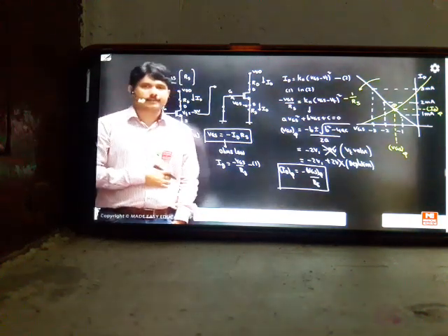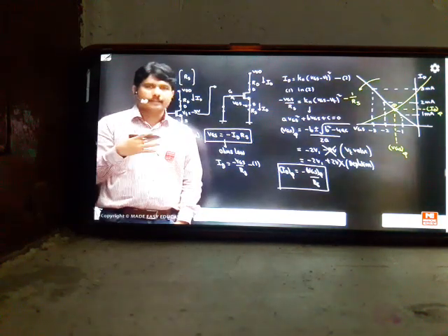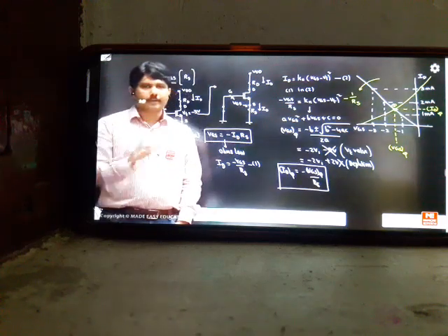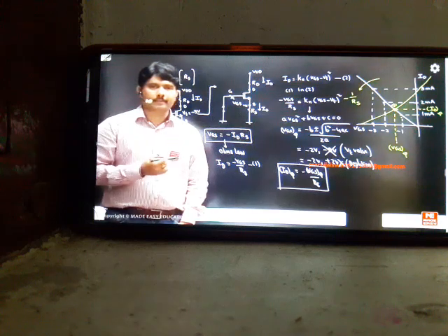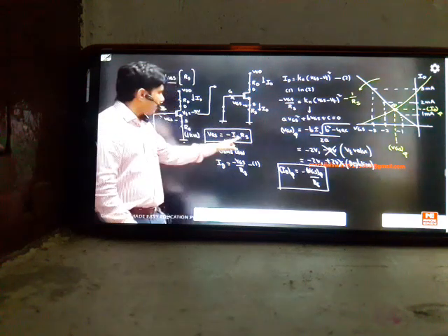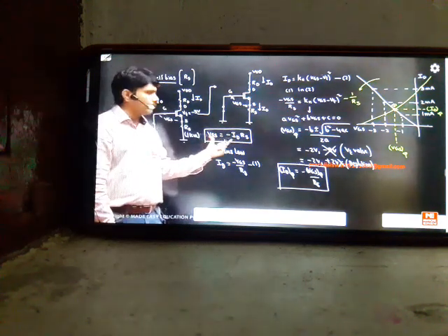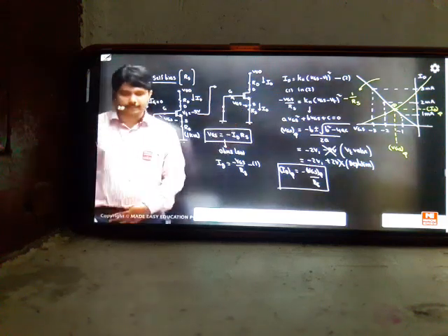You can see how easy this topic is. Self bias means you have some typical mathematics. In fixed bias we don't have any typical mathematics, because the X point we found, the Y point we got directly from the formula. But in this topic we definitely have to go for quadratic methods to solve this type of question. But in 90% of exam questions, in GATE or ESE exams, they give one value and we have to find the other value from the basic equation. So don't forget the equation, Ohm's law equation.